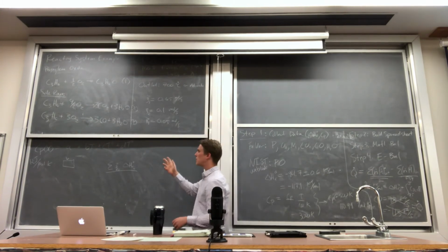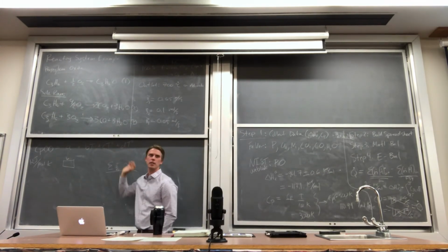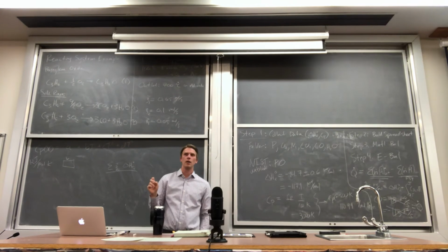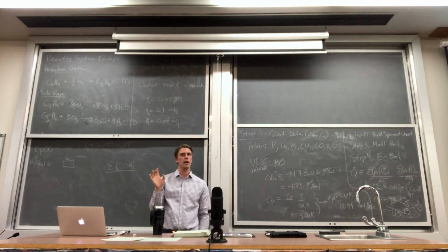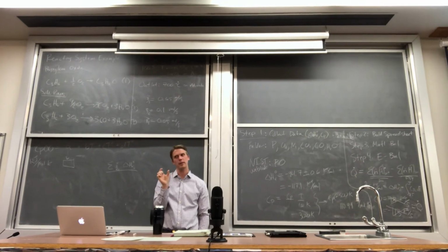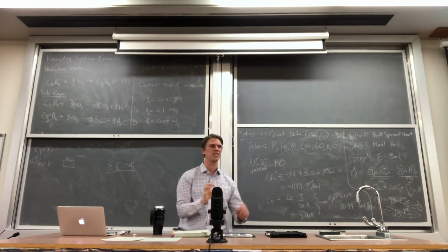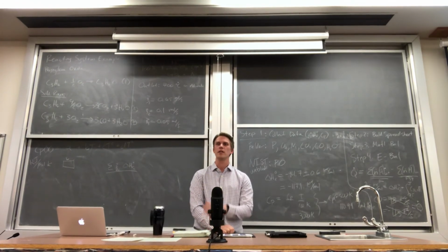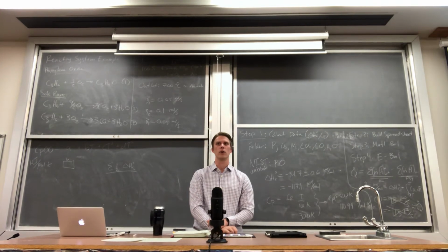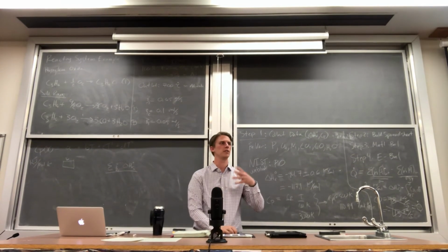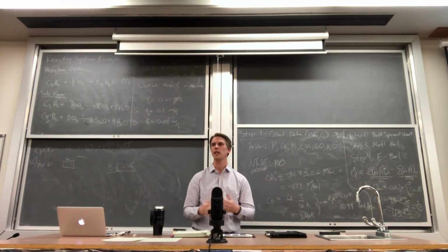So you're probably going to be dealing with a system where you have constant heat capacities. But don't forget, we also talked about the non-reacting system balances being to some extent a little bit tricky as well, because then we have a lot more phase change operations and it's a little bit more nitty-gritty. Because the non-reacting system processes, that's where we typically have separations, changes in composition, changes in phase.